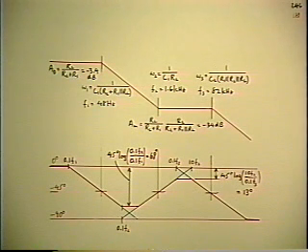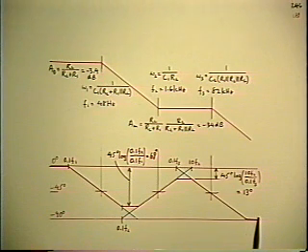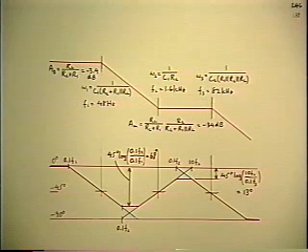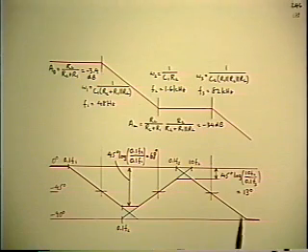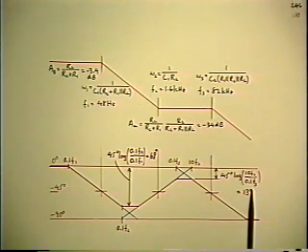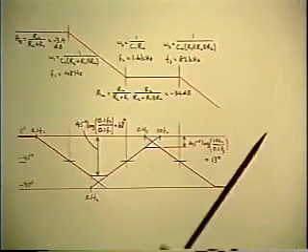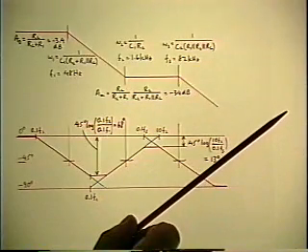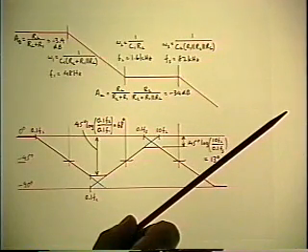They have to do something else as well, because the phase angle is always going to go to minus 90 at infinite frequency with this circuit, regardless of what you change. So in order to bring that back from 90, you actually have to add another element. You have to put another resistor in series with the second capacitor. And all that does is duplicate the problem. Now, up here, you get another phase lead because of the extra resistor.